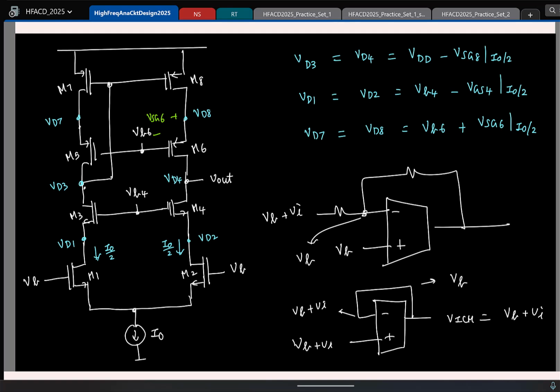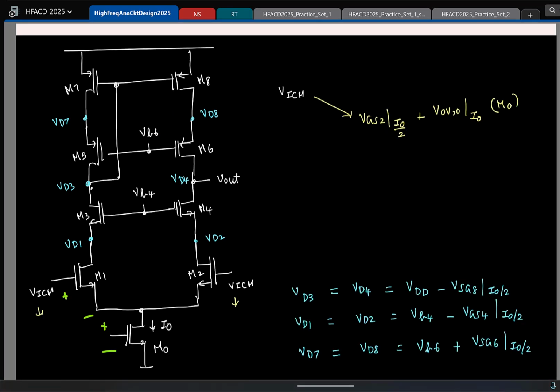Right? So that's why as an OTA designer, you don't have to worry about where it's going to be used finally. You just specify, hey, this is my op amp. At the input common mode, the minimum common mode can go so much, maximum is so much. Now the user can go and back calculate how much will be the range of VBVI based on the end circuit. Right? Okay. So this is the lower end.